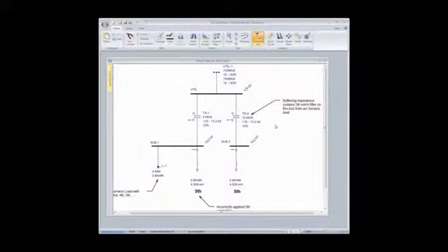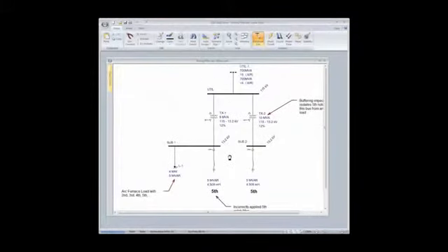For instance, in this case I have up here a quick EasyPower model of a system. I've got a 13.2 kV secondary on these two transformers and a 115 kV primary. It's not a completely stiff source, but it's a 700 MVA short circuit level up here. In this case, I have a fifth harmonic filter that I've tuned to the fifth harmonic.